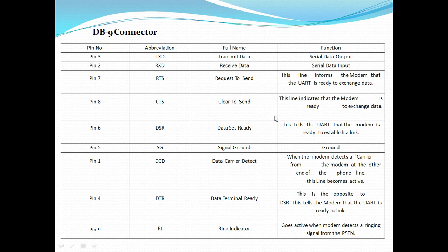Next, clear to send. This is the indication given by modem to microcontroller or to personal computer or to data communication equipment that I am ready to send the data. That means clear to send. This modem will provide this particular signal to communication equipment devices.